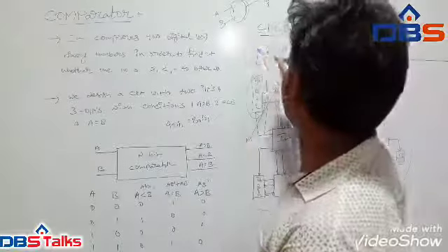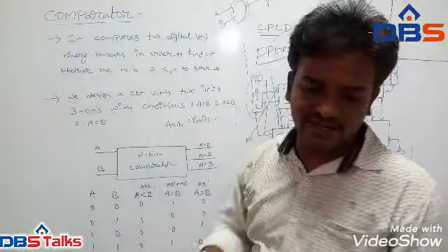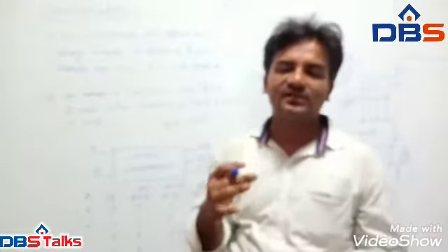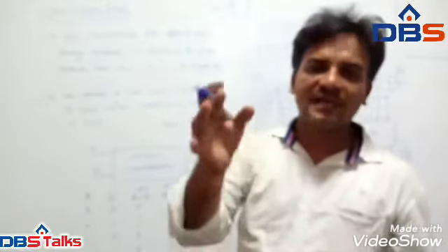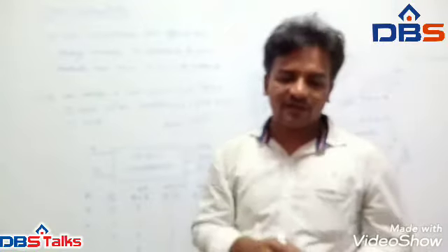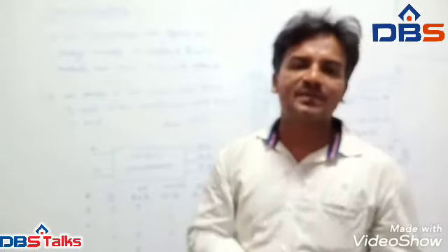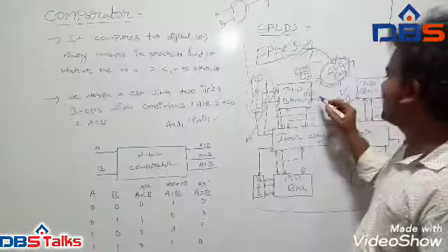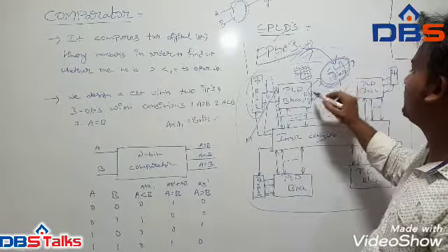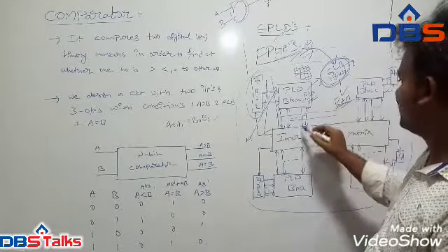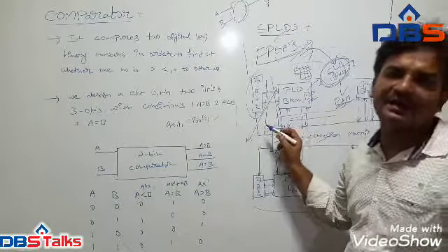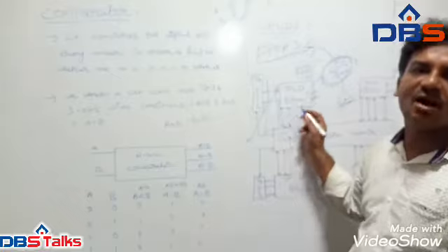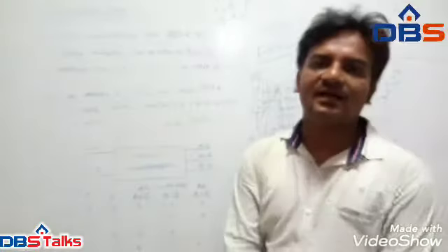Based on that design, once we have successful simulation, partitioning and synthesis, finally we do the placement and routing of each CLB block, and for every IO and interconnection matrix, by using horizontal and vertical routing.